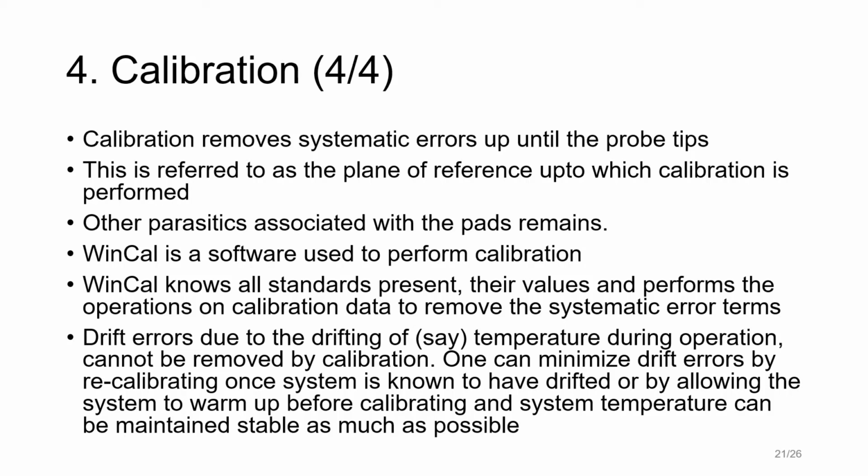However, we would prefer to remove the effects of the pads too and move the plane of reference closer to the device. We will see how the effects of the big pads will be removed in later slides when we discuss de-embedding. WinCal is a software which can be used to perform calibration. Stored in the software and accessible to it is all the data about all the calibration substrates provided by the same manufacturer. It also has the ability to perform many different calibration algorithms.